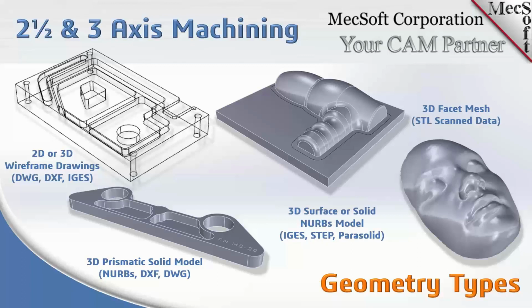You can machine just a single surface in 3 axis. Typically, though, you'll have a poly surface or a group of surfaces, or a closed poly surface, which is actually a solid model. So you can use solid models, open poly surfaces, etc. for 3 axis. Now, the bottom left part, you can use 2.5 axis methods on a 3D solid as well.